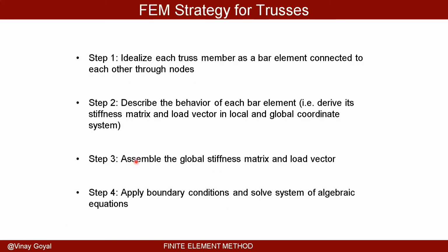So what is a finite element strategy for trusses? The first step is to idealize each truss member as a bar element and connect them to each other through nodes. That's really what we want to do. So we're going to treat each truss member as a bar element.